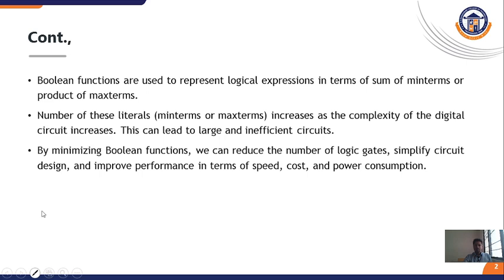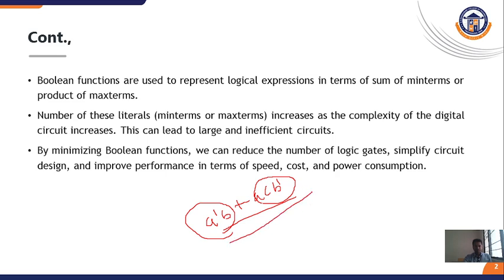That is, if we consider an expression like A bar B plus A C B bar, here this term is a literal, this is another literal. So in this function there are two literals. If the number of literals or number of input variables increases, then this leads to inefficient circuits. So if you are designing it as it is, we have to simplify this function and then implement it.